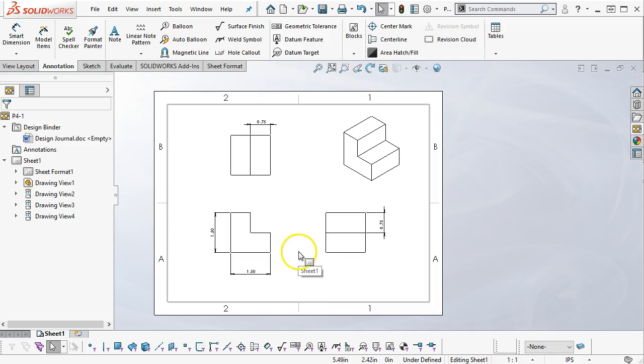But for third angle projection, if we were to take this sheet and fold it over to the back, we would have this view. And if we were to fold it horizontally and over the top, we would have this view, looking down on the isometric. So that gives us our 3 views and enough dimensions to make the part. We don't have anything on this blank sheet for material, finishes, or other pieces of information that'll be useful in the manufacture. So let's go ahead and save this.